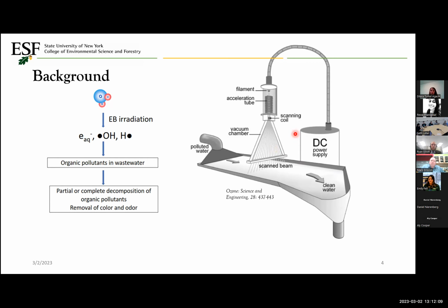Radiation dose is the only important parameter to control the irradiation process, and it is determined by the beam current and the water flow rate. Both parameters can be used to adjust the desired radiation dose for the electron beam treatment. Therefore, the process is extremely simple, and the automation for this treatment method is very easy to perform.